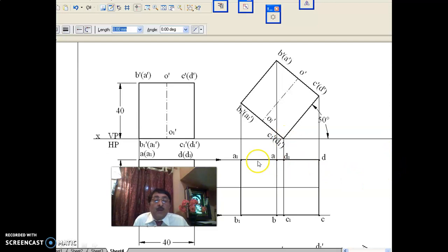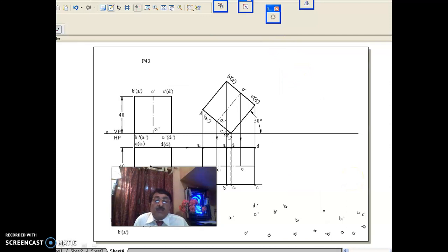See here, in that way, first the outer boundary I have done. In the outer boundary itself, if you see 4 points here, 4 edges, 8, 9, 10 have already come. Now since the top surface is nearer, darken the top surface, A, B, C, D. And the remaining edges of the other surface, make it dark dotted, means it is only C1, D1 that you make dark dotted. That is, in fact, the edge on which it is resting. For an observer who is looking from the top, it cannot be seen. Now show the axis also, O1.